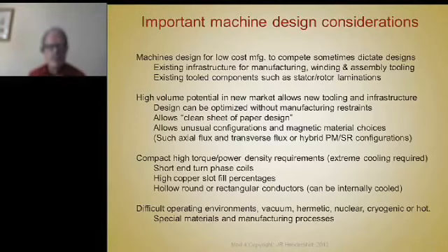How do you make a premium-efficiency motor? You use more expensive lamination materials that exhibit lower core losses. You put insulation on each one of them. You might even have to anneal them, post-process them after you stamp them. And then you stuff the slots full of copper. You use larger wire gauge or more strands in parallel to get the current density low.